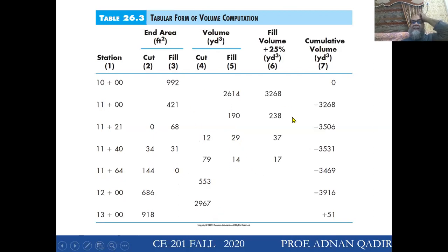And since the fill areas, whatever you get out of the cut, there is an expansion factor, say 25%. It's very simple. If you have 1 meter by 1 meter by 1 meter depth, obviously the volume will be 1 meter cube, but that is a cut volume.